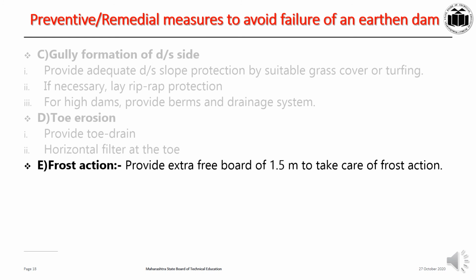Then frost action. Provide an extra freeboard of 1.5 meters to take care of frost action. These are the prevention or remedy measures to avoid hydraulic failures.